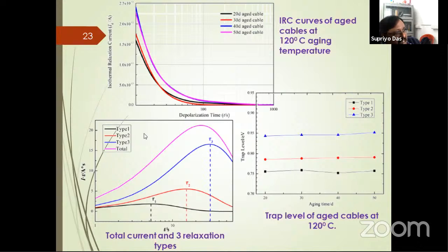H has a possibility it can capture an electron and get neutralized. If C captures a positive ion after bond breakage and gets neutralized, that means that particular positive ion is trapped. Because of aging, such breakage of bonds is more, the deterioration is more. So in that case, formation of traps also increases.